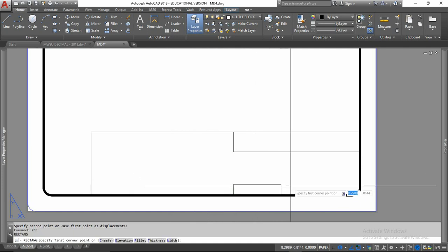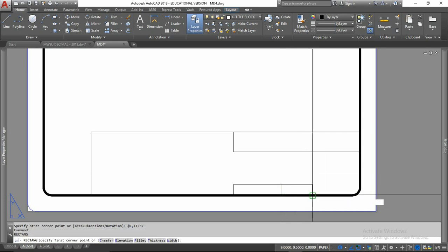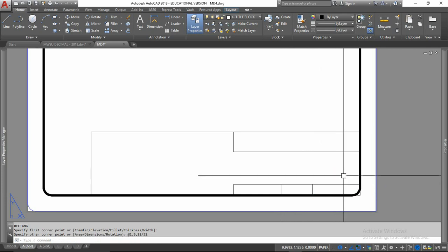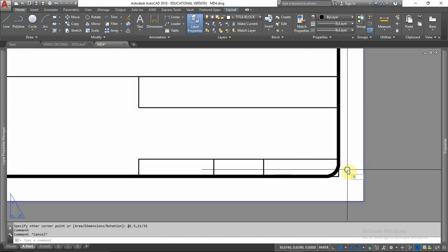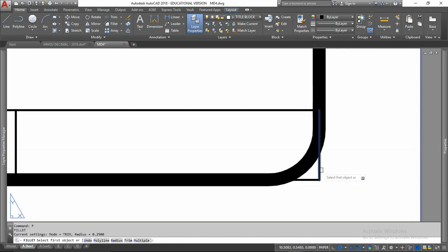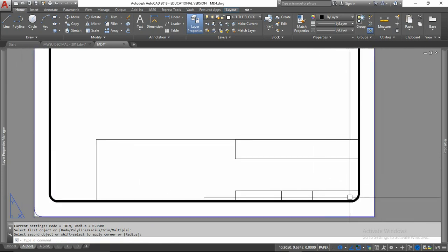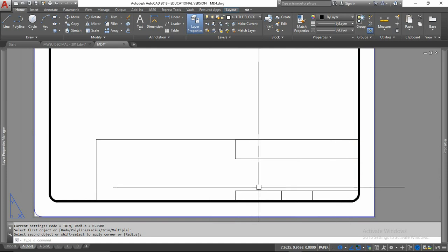So now another rectangle from this point, and that is a 1, 11/32. Another one here of 1.5, 11/32, which should end up right there in the middle of this and that. So again, I'll fill it that again. Now, some of this seems to be a little redundant over and over, and that's true, but again, this is the title block. This is a little bit different than other normal drawings.